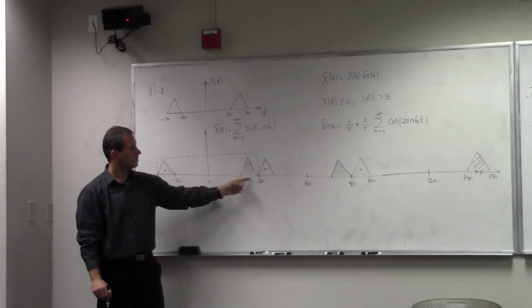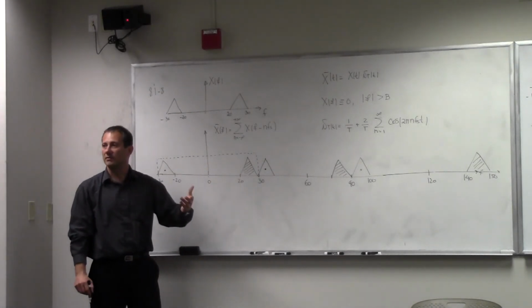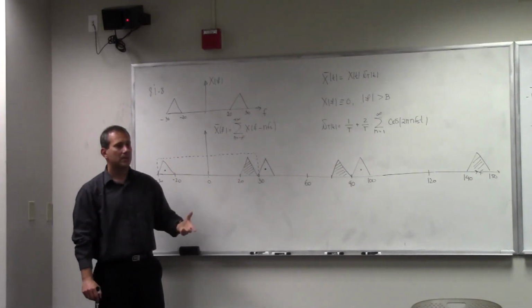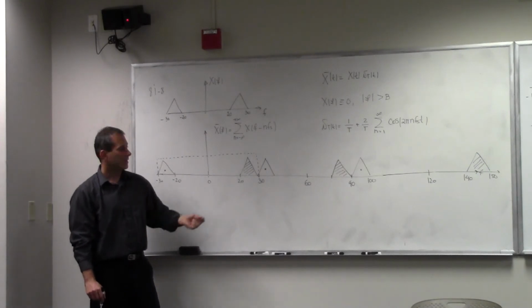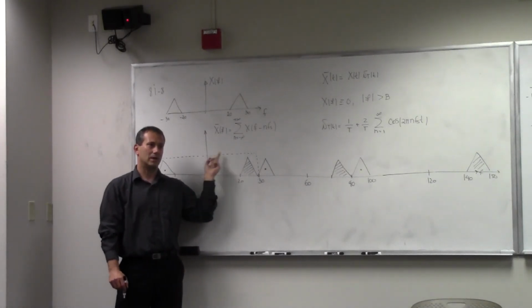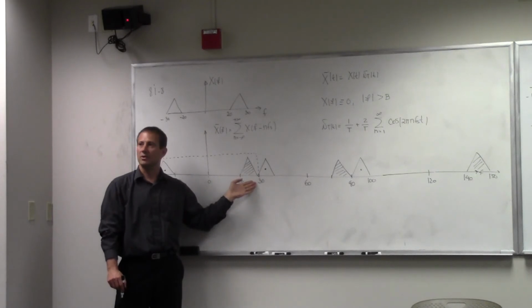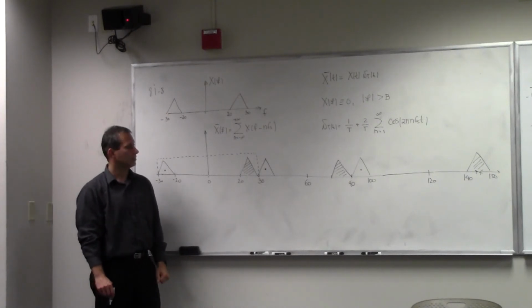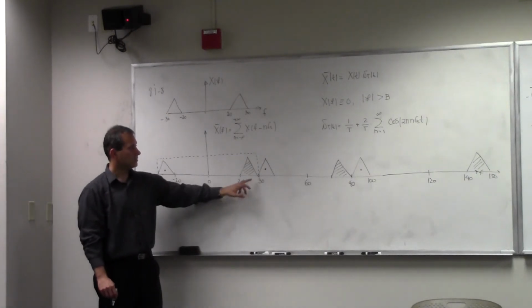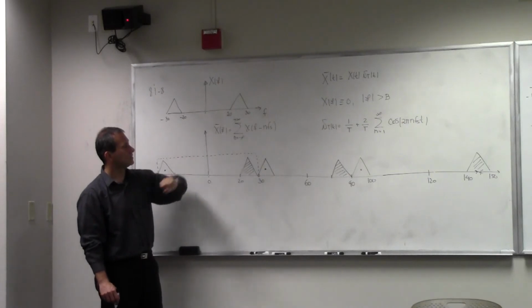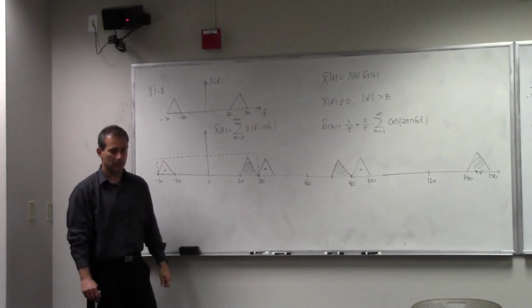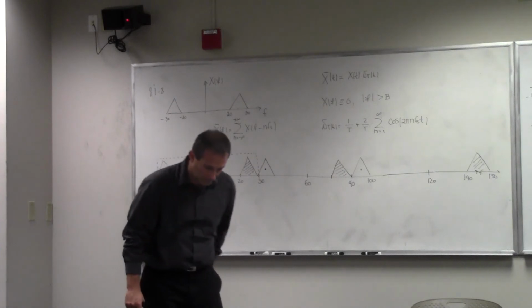Low-pass filter in the frequency domain is essentially that sinc weighting function in the time domain. Right? So here, I'm actually sampling at a Nyquist rate. So I have no wiggle room, and I would have to have an ideal filter as my reconstruction filter, which is physically not possible, right? So that's why, if I sample the signal at 60 Hertz, I'm just satisfying the sampling theorem theoretically, but practically I would have a hard time reconstructing this signal.